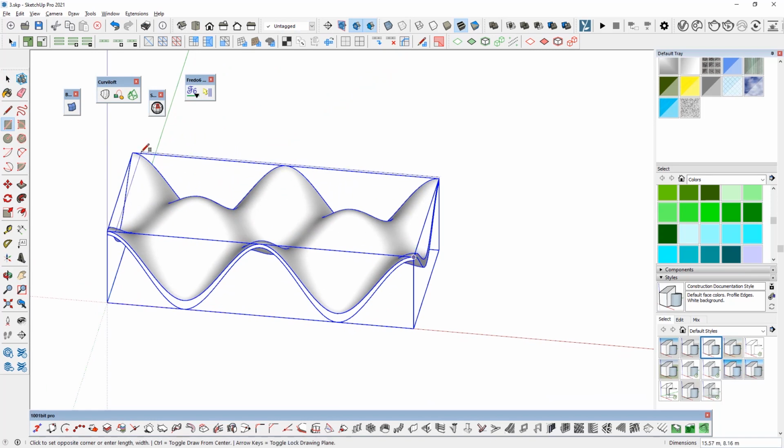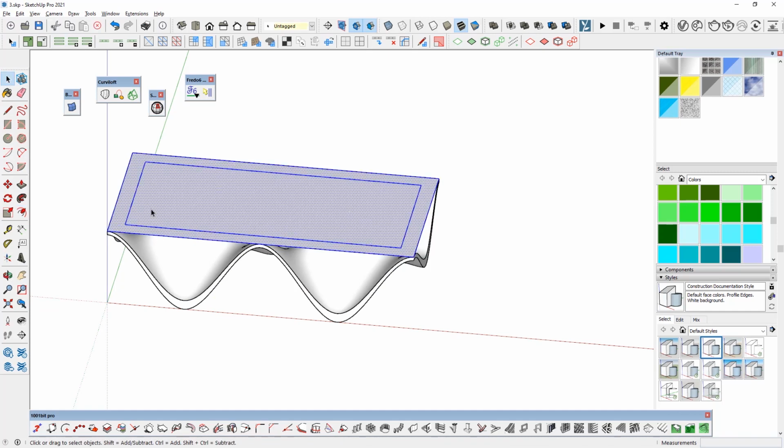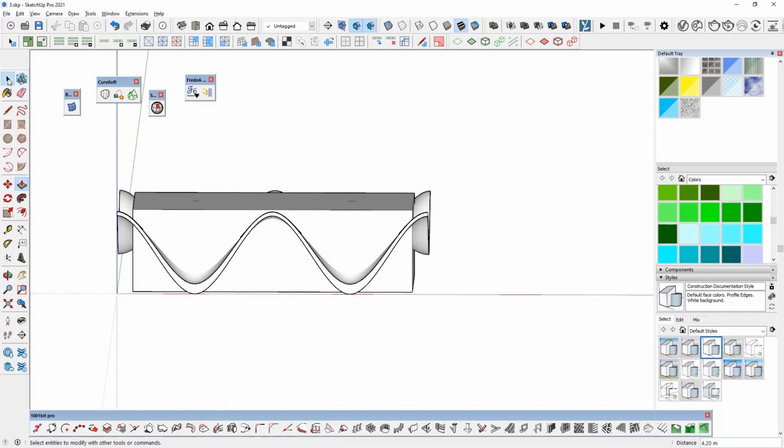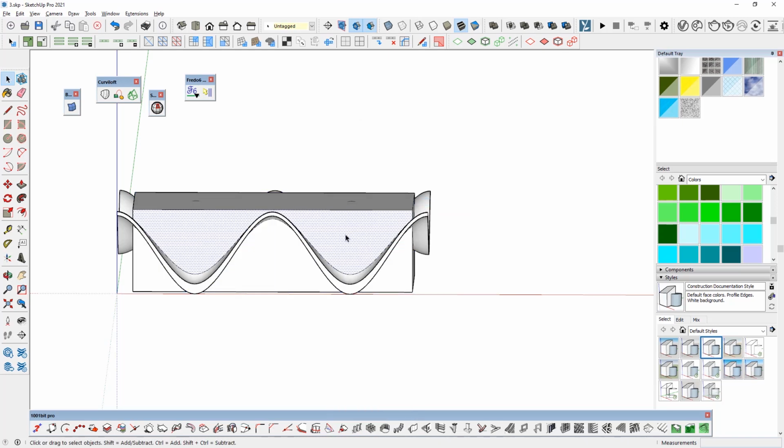Now we need to select the upper rectangle, also with the offset about 0.8. Now we need to triple click, and with Ctrl and left Shift we need to click in the middle one to select the outside surfaces and remove them. Then we need to use push pull, and we need to select the new solids and use intersect faces with model.